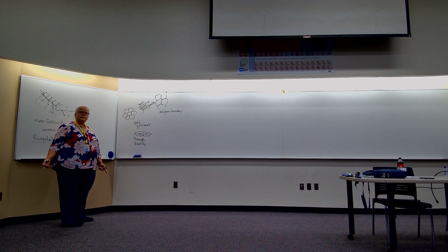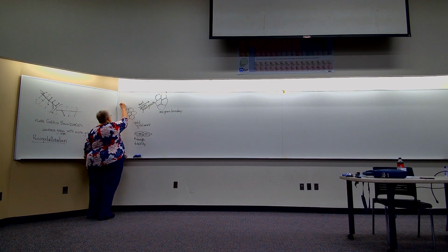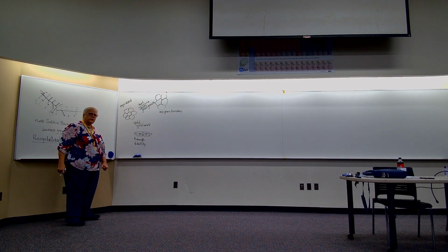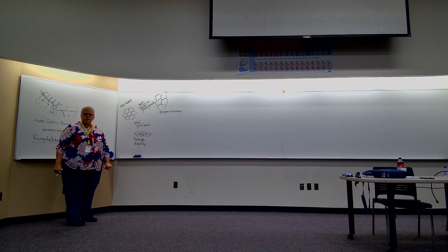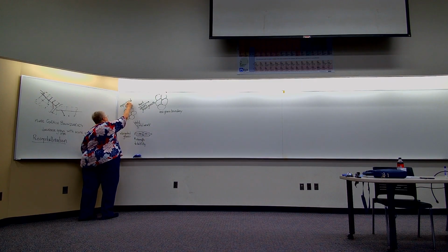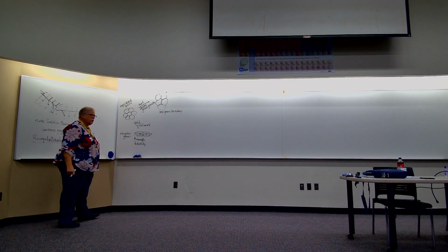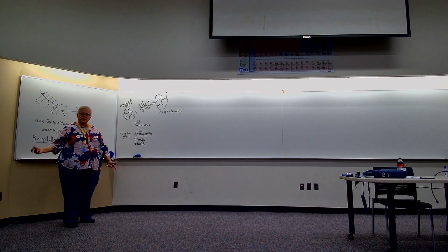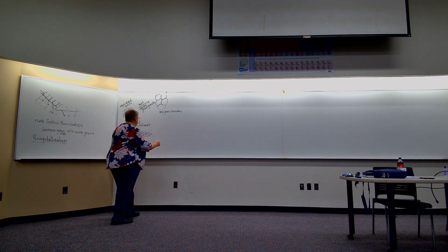If we were to describe the structure, these grains are called equiaxed, meaning the same axes, meaning they're approaching spherical. After cold work, I have elongated grains. So step one in this process is cold work, which we're familiar with. Then, after cold work, we add heat.